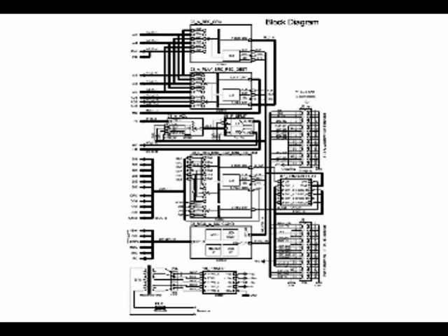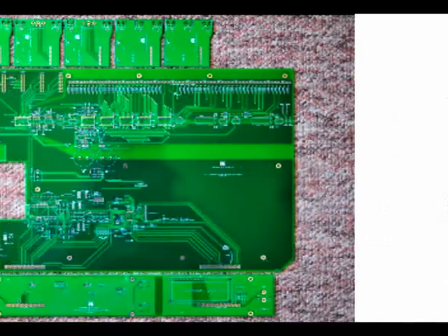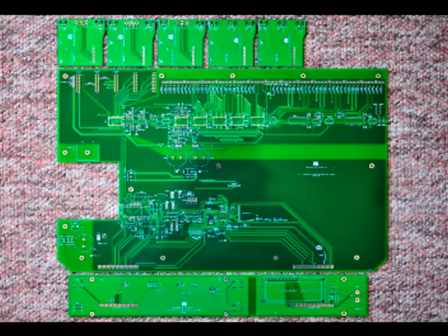The central control for the Switchbox is a microcontroller, that is, a microprocessor with inbuilt peripherals, that handles all the selector signalling, commands from the front panel controls and liquid crystal display, and communications with the outside world, the touch PC and the miscellaneous drivers board, amongst others. Also within this module is an LED driver for the infrared LEDs that control the various components of my hi-fi system. From that block diagram came circuit diagrams for each of the modules, and then came printed circuit board layouts.